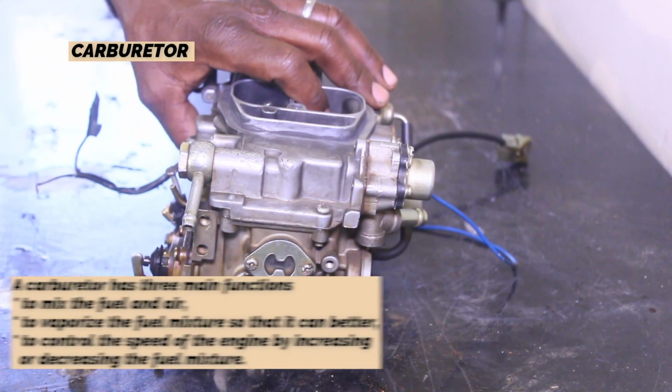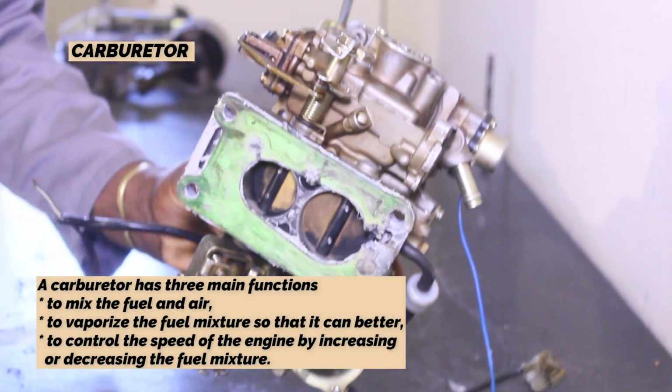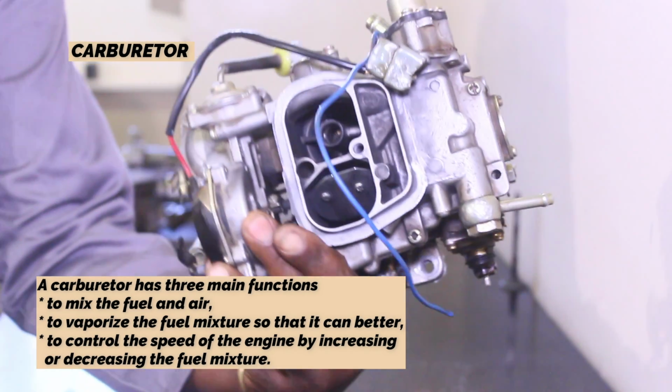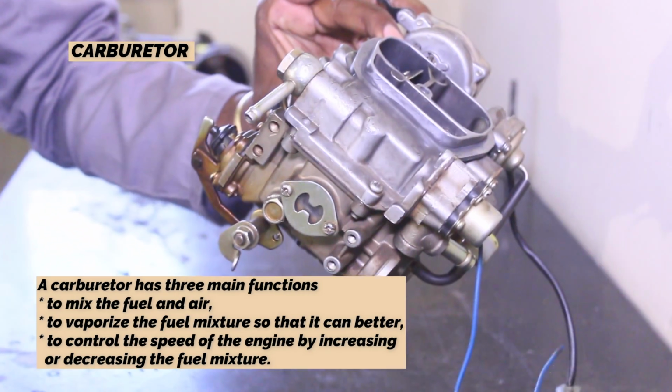Carburetor. A carburetor has 3 main functions: to mix the fuel and air, to vaporize the fuel mixture so that it can burn better, and to control the speed of the engine by increasing or decreasing the fuel mixture.